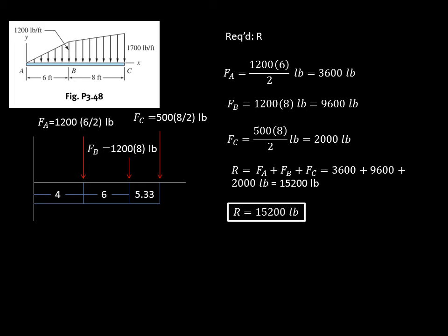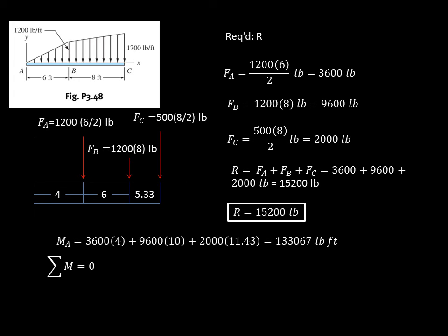First, we assume the moment center. In this video, point A is the moment center used. Points B and C can also be used as a moment center, and they should yield the same answer. Next, we establish the moment equation with respect to the desired point to solve for the resultant moment.